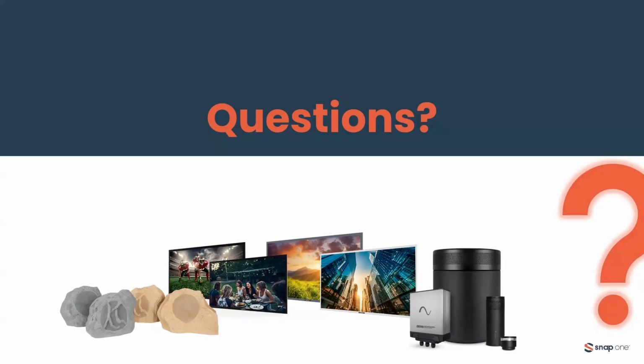Yes, Paul, on the mono stereo question. Yeah, so I don't recommend trying to do a stereo system outdoors. Typically what you don't want to hear is the vocals coming from one side of the yard and the guitars coming from the other side of the yard. You're much better off getting a more consistent mono experience of all audio hitting you at the same time. And that's pretty much, from every conversation I've had in the industry, unanimous. Most people prefer mono systems outdoors. Yep.